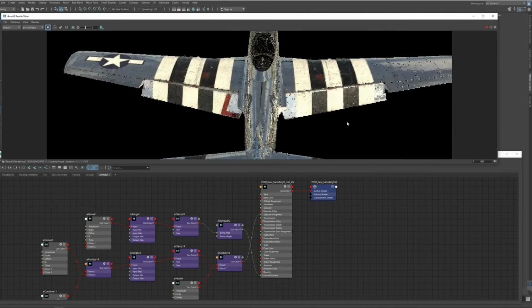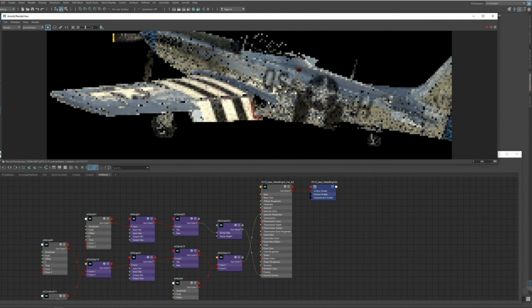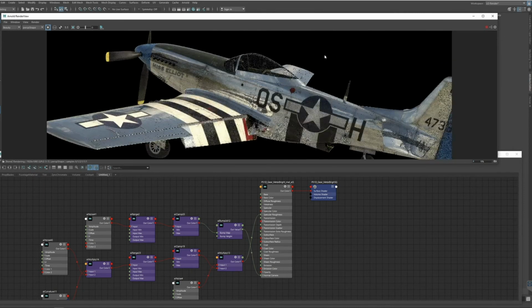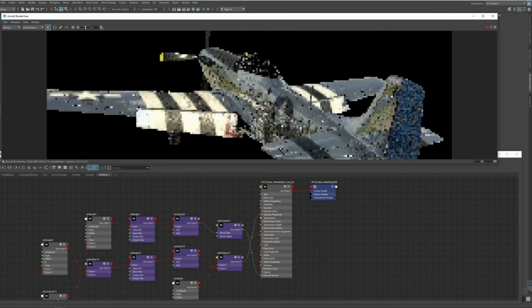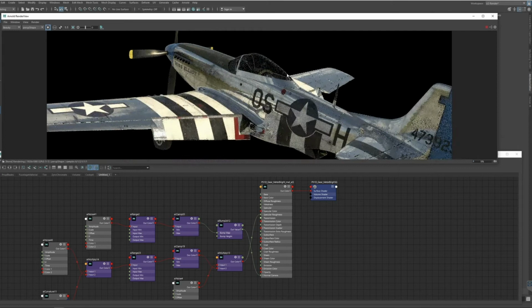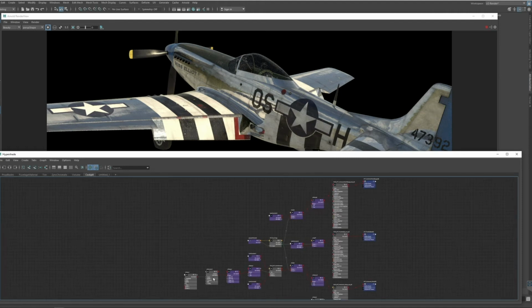So we can move our camera around right in here in this Arnold render view, which is pretty practical. I don't have to switch to the viewport at all times. So if I am just shading and connecting nodes, I can just move about in the IPR up here. And one thing that you might want to do when taking a look at shading networks, whether you're trying to find out what somebody else did, or really if you're developing shaders and testing your materials,